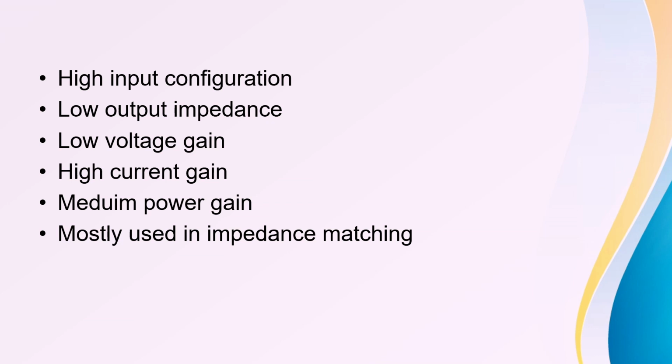It means that the output impedance of a circuit is very high, and the input impedance of another circuit is very low. These both cannot be connected because loading occurs and the efficiency of transfer of the current is very poor because of this variation in impedance.